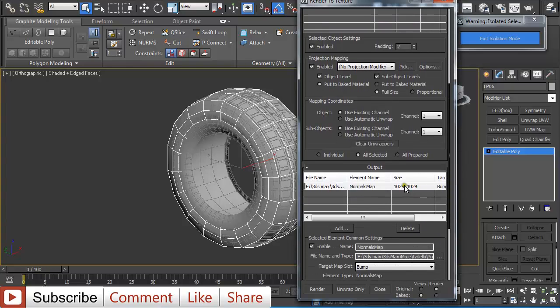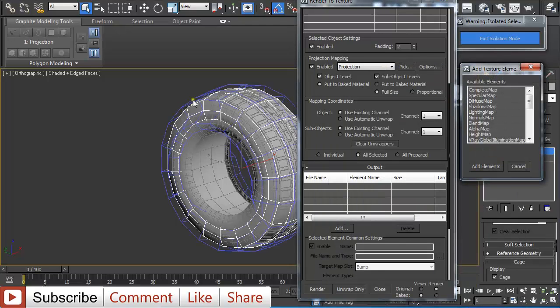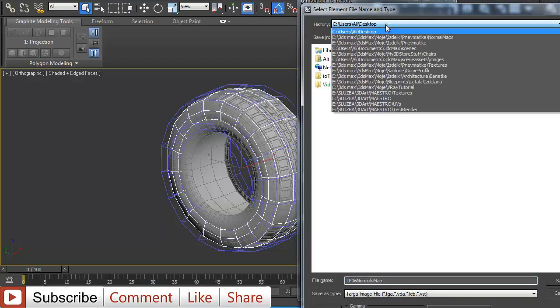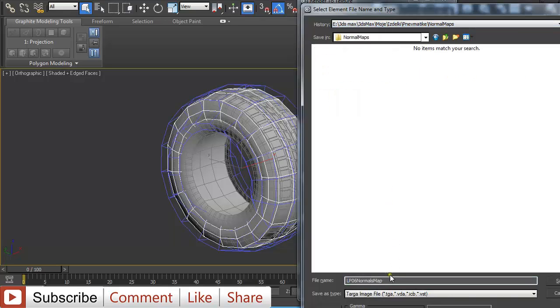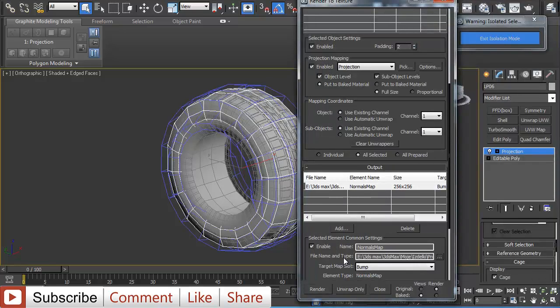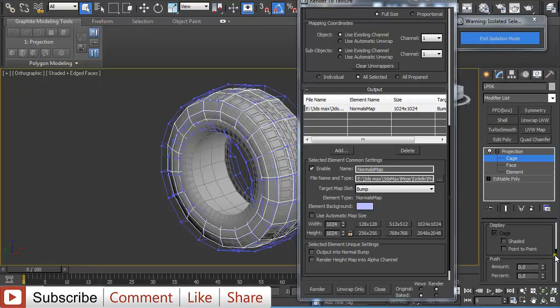but before, now we first have to delete this one or it's not going to work. Pick high poly version. As you can see, the projection is added. Normal maps, add element, again name it, and 1024, but first I'm going to go to projection, cage, and shade it.